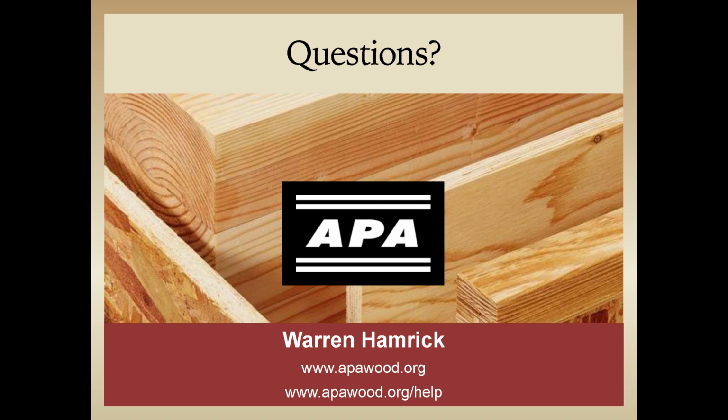In some of the colder climate zones, we try to make everything as nationwide as we can, which obviously doesn't work in all situations. So in some climate zones, they're using 2x6 already at 16. Can they still go to 24? How does that affect them? I'm not sure on that. I think you would have a slight reduction in strength in some directions, but I believe, and we'll clarify this in the Q&A that we post, if you're designing per the IRC, you should be able to go to the 24-inch spacing without an issue.